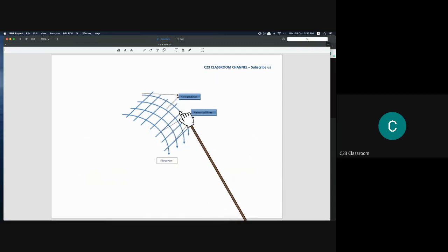Okay, let's say this is the streamline. Normally when you draw a streamline, you will put an arrow mark because it's showing that the flow is from left to right or top to the bottom and so on. And if you draw a potential line, normally we draw a line without any arrows, because the potential line is actually just to divide them into certain cubicles like this, because it will help us to calculate the conservation of mass inside this mesh. That's the basic idea of the calculation.